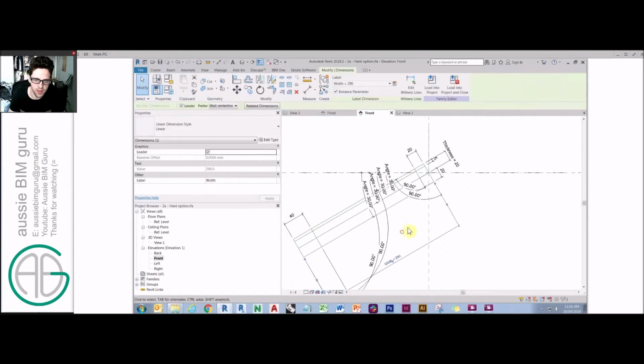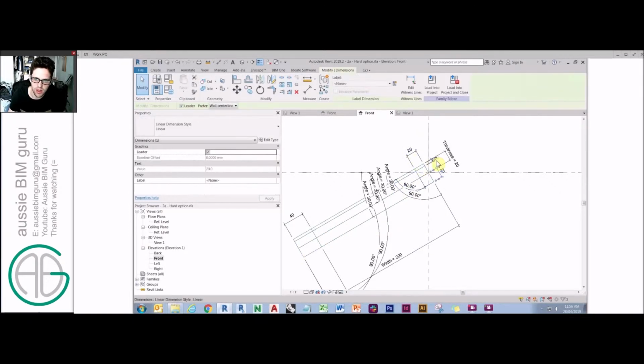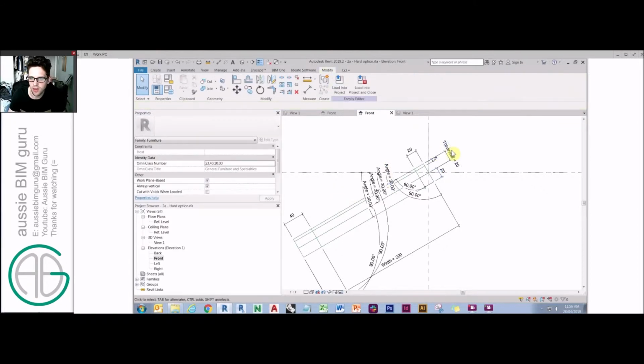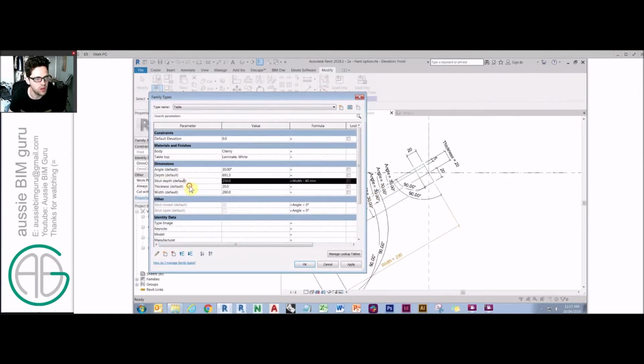And then from there I've just set a few 90-degree relationships to the ends, and then set up some dimensions and locked them down to particular sizes, and then assigned a thickness parameter. So essentially what you end up with is an angle, and then all the geometry sizes. We don't actually need this anymore, that's from what I copied it from. And then from there I've just got a visibility parameter that basically says the strut will only be in the open position when it's at 0 degrees.